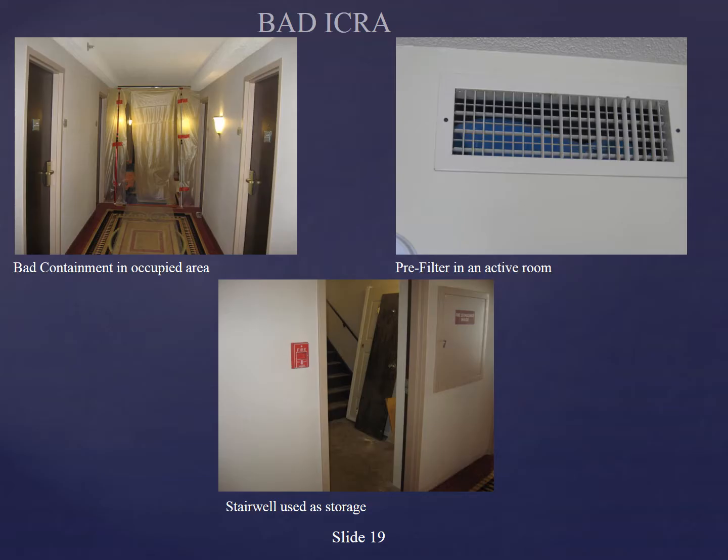Here is a bad ICRA. This was a common practice and still is. I remember years ago when we got those little extending poles with plastic, we were like, yay, we have a quick answer to do these jobs. And I cannot begin to tell you how ineffective that really was, primarily because we just couldn't tape and seal it right. The other thing about this too is you can pretty much see through this plastic.